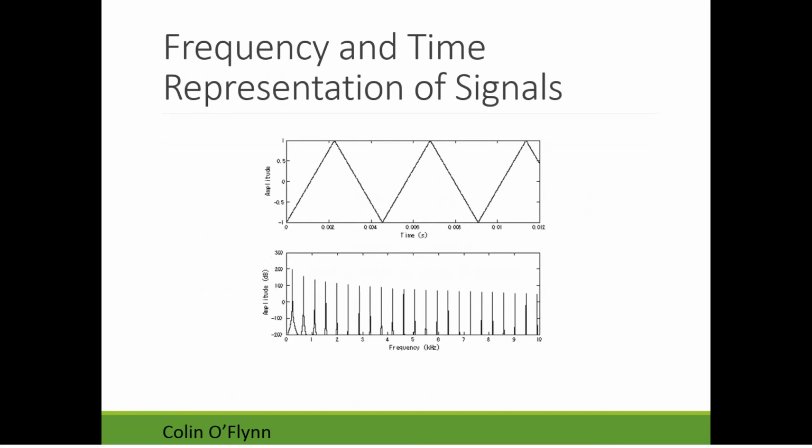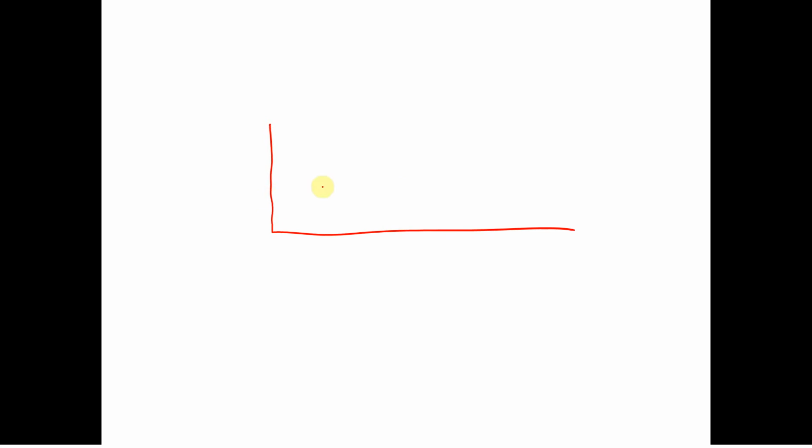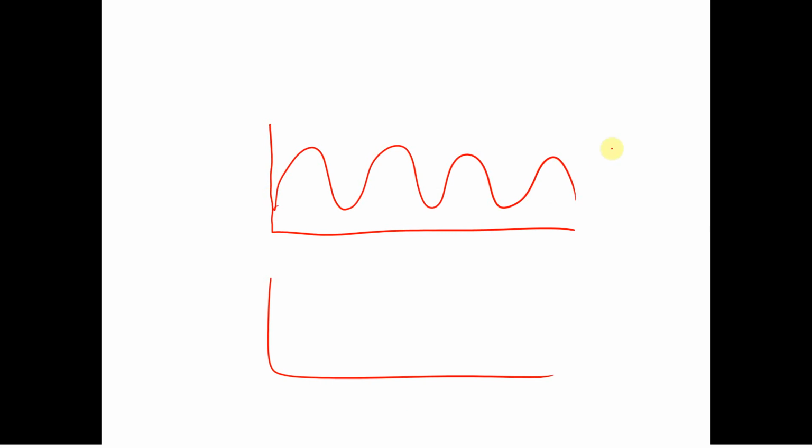All right, so the final thing to talk about today is filtering. So very briefly, filters look at the signals in the frequency representation, which is what we care about. So all signals have some associated frequency representation. You should have done this in some of the other classes. But the most basic is something like a sine wave. Hypothetically, a pure sine wave just has the single frequency representation. If this is a 10 megahertz sine wave, we just have a 10 megahertz frequency component.